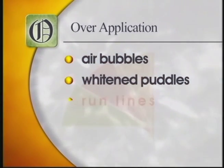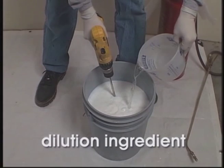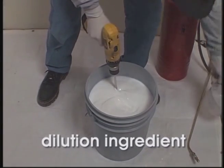Over-application may cause problems, such as air bubbles, whitened puddles, run lines, and delayed or improper cure times. Preventing these problems is critical to a successful finish. Certain primers are diluted to achieve a lower viscosity and to prevent the previously mentioned problems.